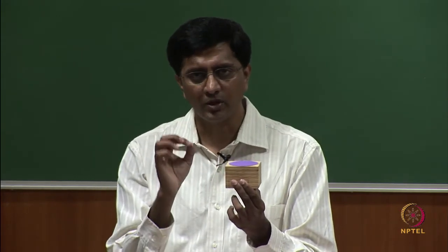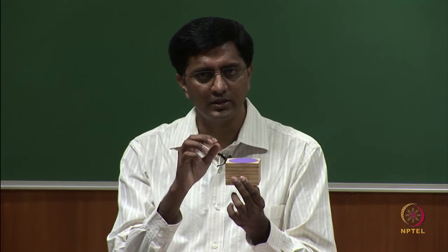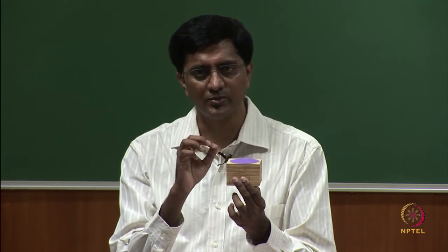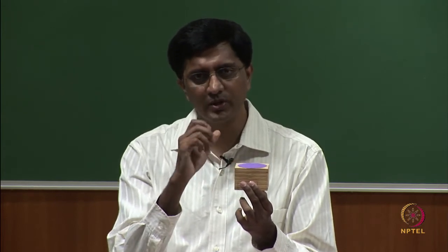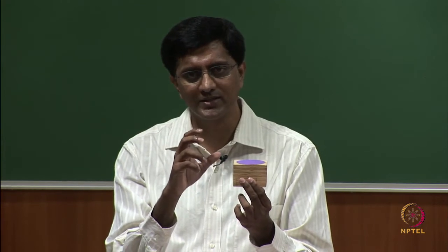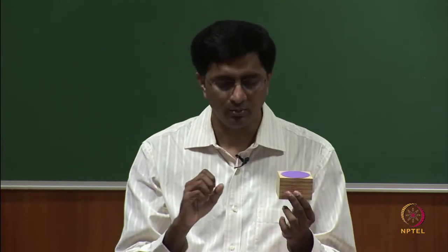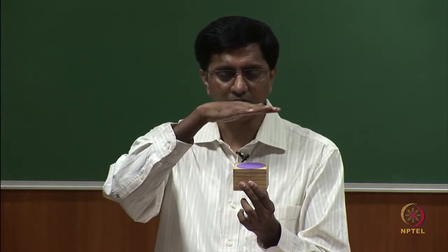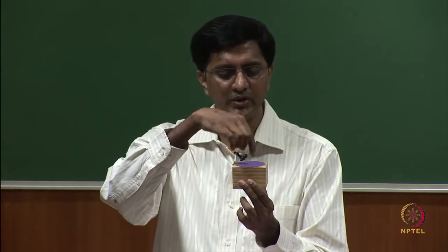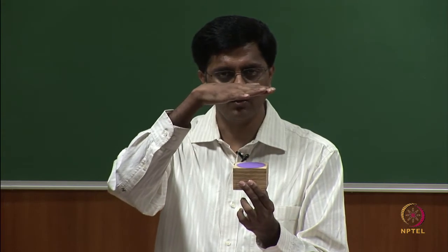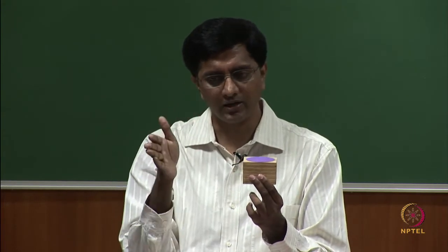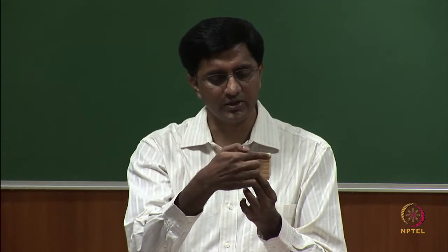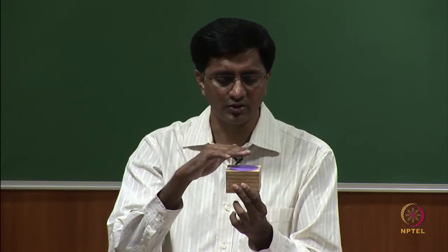Okay. The point being is, then it becomes easy to draw the isometric drawings, and it also becomes easy for you to understand it from the multi-view drawings. All these faces, when they are parallel to one of those planes, appear as an area in one of the planes, and in the other 2 projections it only appears as an edge. So, let us focus on the top view.